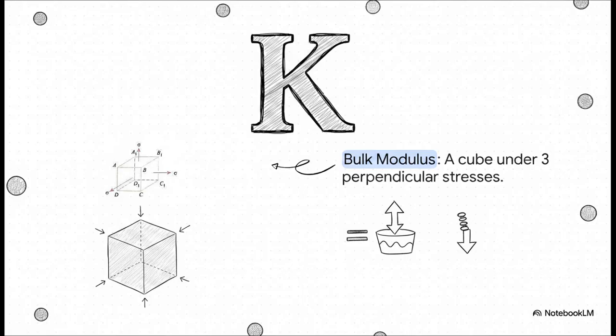Let's actually visualize the bulk modulus, K. Picture a perfect cube being subjected to three mutually perpendicular tensile stresses of equal intensity. Bulk modulus is the ratio of that direct stress to the volumetric strain. Basically, it's a measure of how well a material resists a change in its volume under uniform pressure.